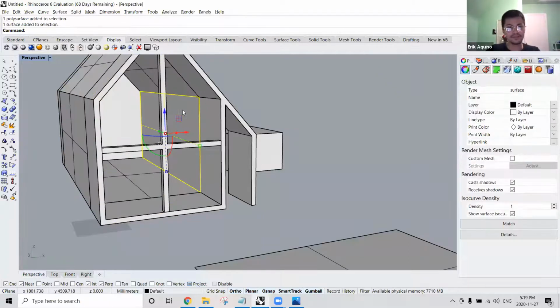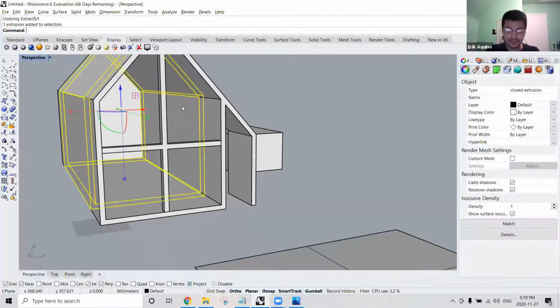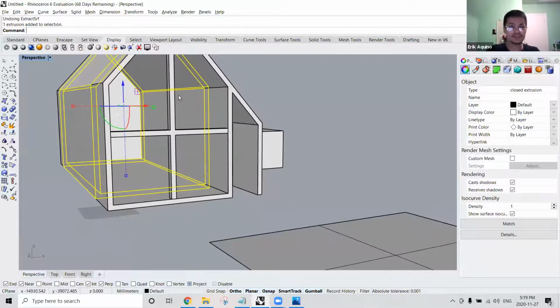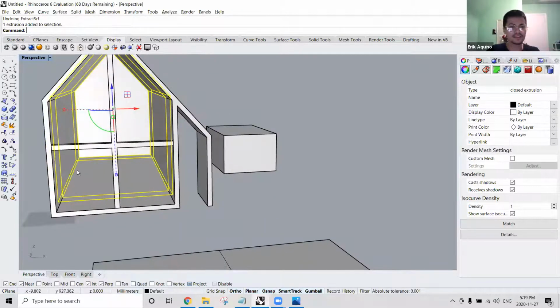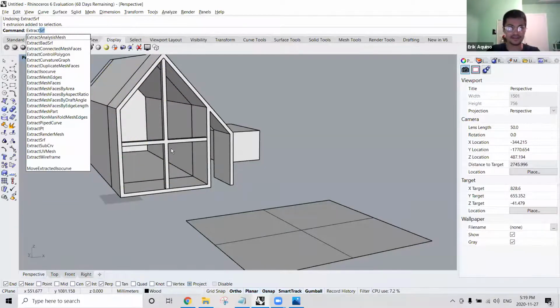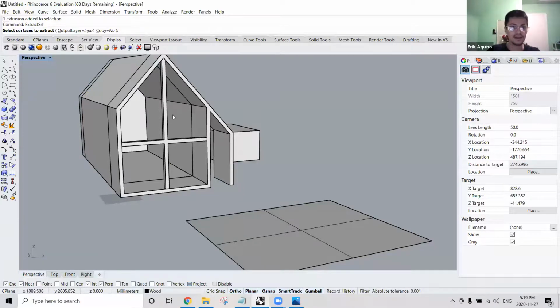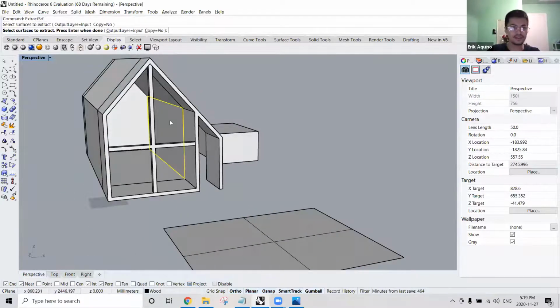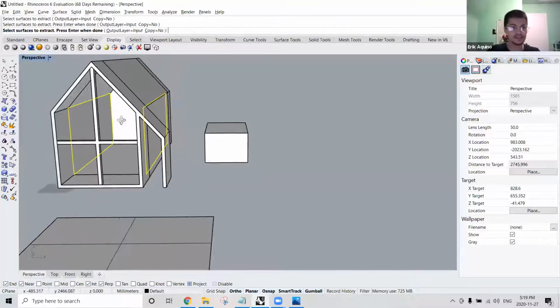Yeah, so I extracted a surface, meaning I specified one of the faces of this object, and there's many faces: on the outside, on this perimeter edge, on the other perimeter edge, and on the inside. So I could use extract. It's different from extrude. It's extract surface. And I'm selecting a face, or I could select multiple faces.